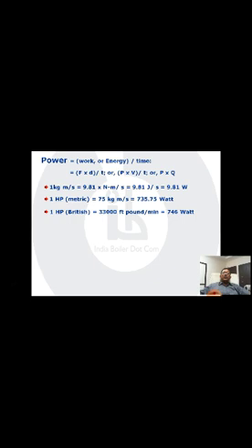Now, talking about these equations, F into D by T is power, P into V by T is power, because PV is work, and V by T is the volumetric rate of flow, that is the discharge Q. Now, this P into Q is a very, very useful equation, quite often used, primarily to find out the power of fans and pumps and such.